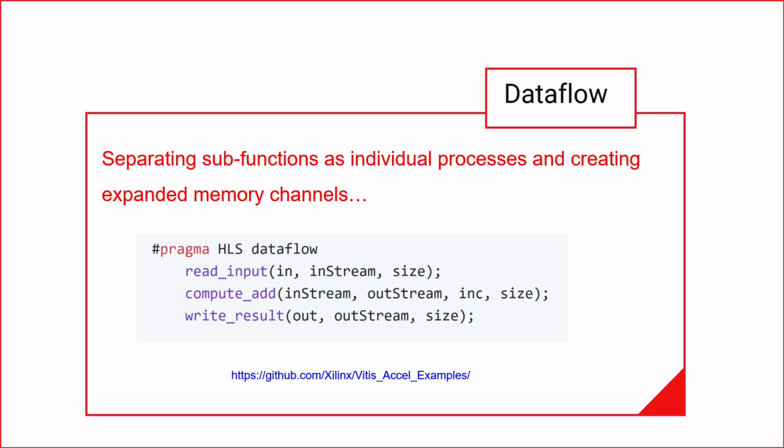Note that DATAFLOW optimization potentially improves performance over a statically pipelined solution. It replaces the strict, centrally controlled pipeline stall approach with a more flexible and distributed handshaking architecture, using FIFOs or ping-pong buffers to connect between the tasks. The replacement of the centralized control structure with a distributed one also benefits the fan-out of control signals, for example register enable, which are distributed among the control structures of individual processes.